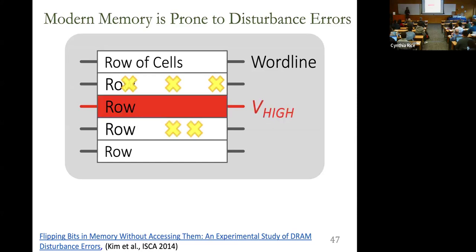It turns out in modern DRAM chips, some cells that are vulnerable in physically adjacent rows get corrupted. So you lose data. This clearly should not be happening. Nothing should be changing in DRAM if I'm doing activate, precharge, right? Let alone other rows, which may be belonging to some other application or the operating system. So clearly, this is a reliability problem.